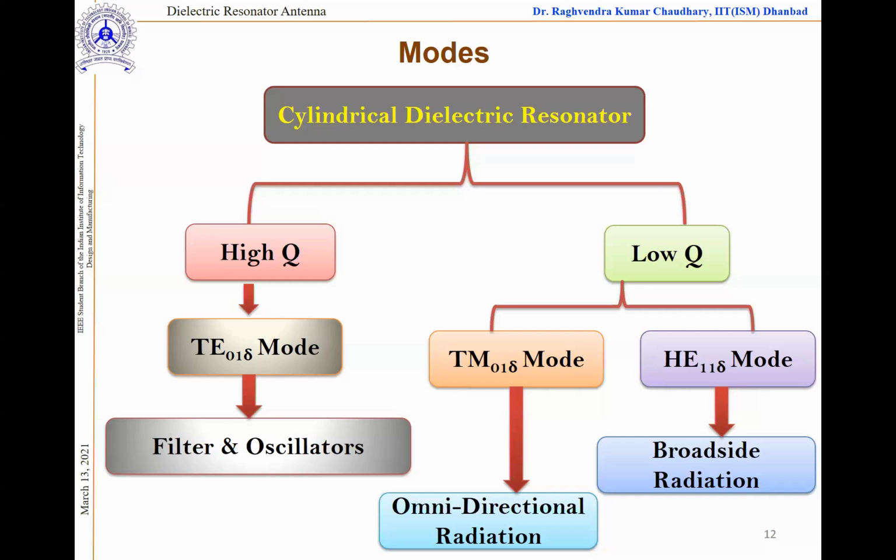You can also use the TE01δ mode, because maybe some far-field requirement you can fulfill with this TE01δ mode, but maybe the efficiency and other things you have to compromise. In many papers you will see the TE01δ mode also used as a radiator.